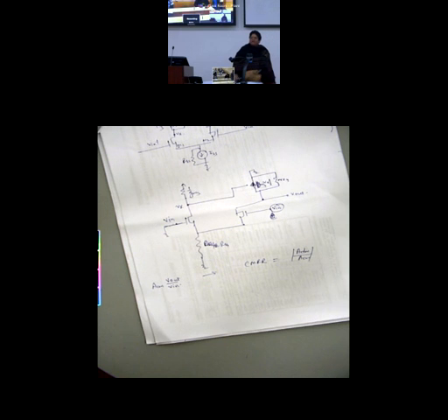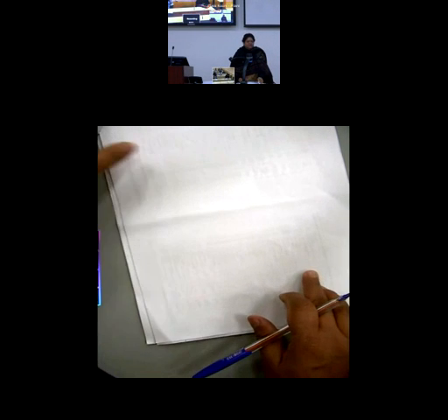Okay. So we have got current mirror acting as active load. With active load, the analysis has been done. You know the two topologies: fully differential, where you give your input differentially and take the output differentially, and a current mirror load topology, where you get a differential input, but your output will be a single-ended output.